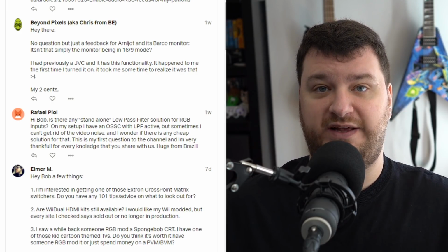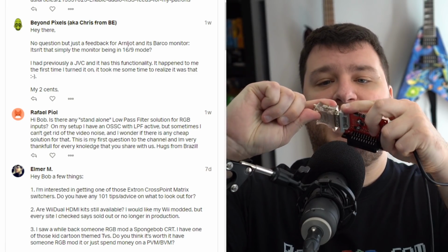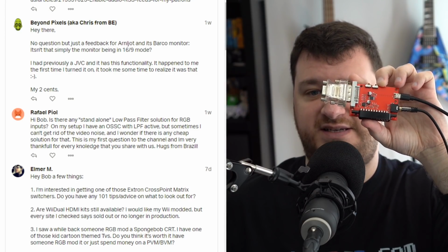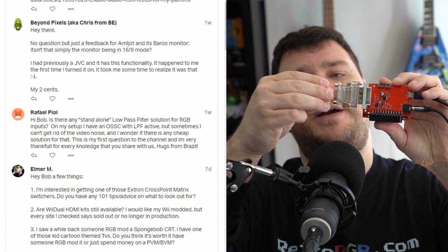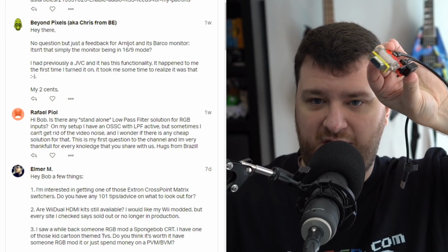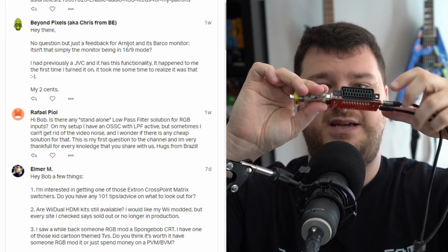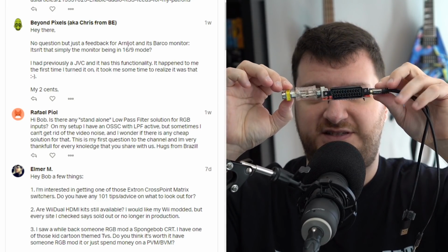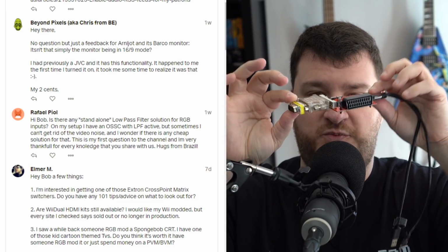So if you wanted something like a second SCART input, you could use just a DVI adapter, because remember, this is just an output connector. This isn't a DVI signal, it's just analog output. So use a DVI to VGA connector, then use just a VGA coupler, and you could plug this directly into the VGA input of the OSSC, flip on the low pass filter you have here, and essentially what you have is now a second SCART input for your OSSC with an external low pass filter.